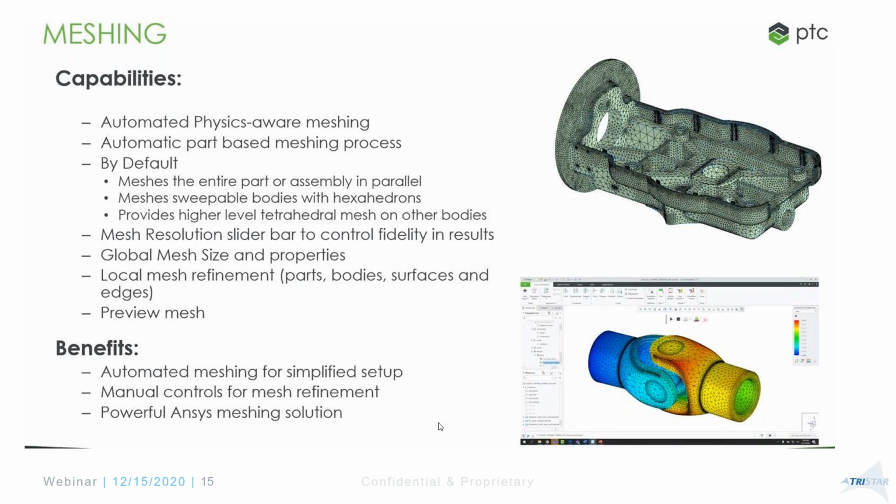So depending on the geometry and depending on what type of analysis you're defining, it understands to control the mesh automatically, and there are some default settings that you could change, or if you're a new user, you could just use a slider to refine the mesh, or sometimes it's a good trade-off in there.